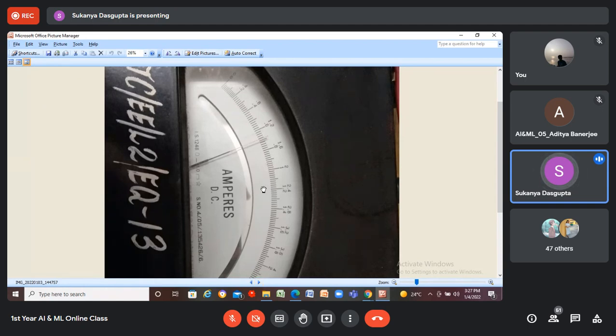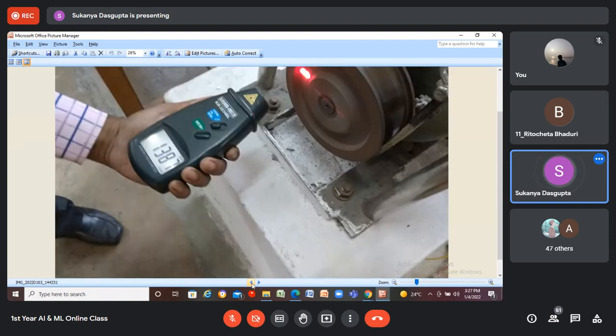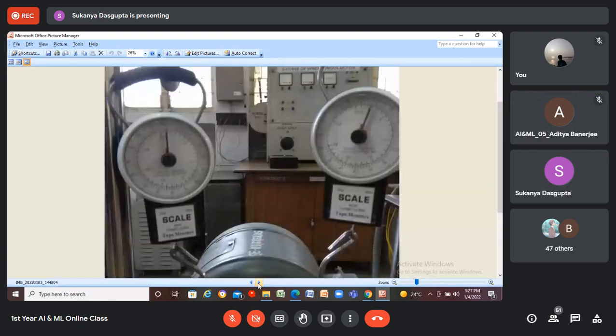And what is the armature current? It is in between 1.2 and 1.6. 1.4, right. It is kept at 1.4 by adjusting the rheostats only. So what is the speed? 1387 or 88. Yes, ma'am. 1387. Okay. Next, again we'll vary the load.